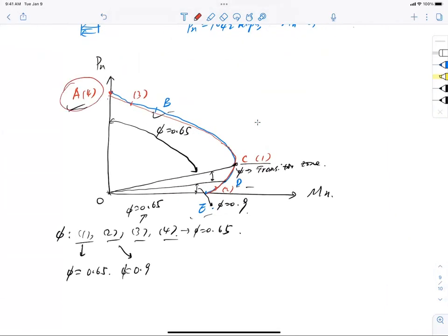Pure axial load. Now we did 3, we didn't do B, but the difference is that for 3, we say c equal to 18 inch. For B, c just equal to the entire d_s, and that is 17.5 inch. Okay, now for C, we did that already. You know how to do that. We didn't do D, we didn't do E. For D, it's actually epsilon_s equal to 0.005 instead of the 0.075 we assumed in the example, right?